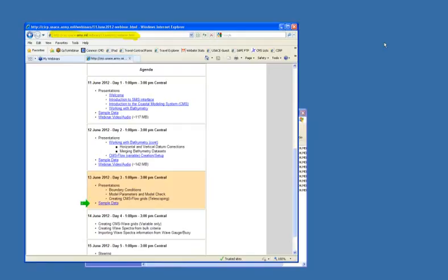Okay, now back. So what we're doing is we're basically taking the grid and or the scatter points with our refine points. We have our grid frame here in this purple grid frame, and we can go under Feature Objects and convert that to a 2D grid. I have to go back and set this up again. So we're choosing the bathymetry here, an extrapolation value. I used, I think, -2 yesterday.